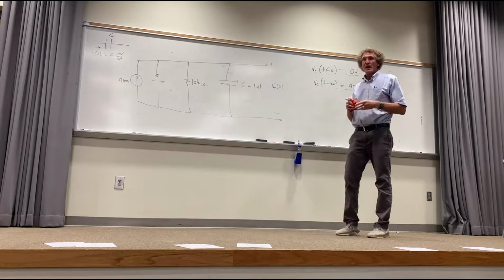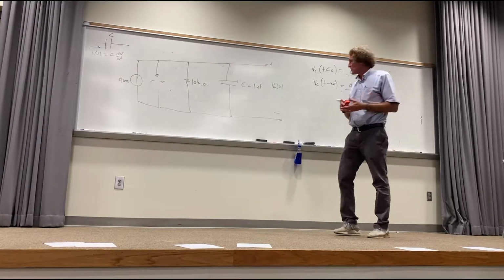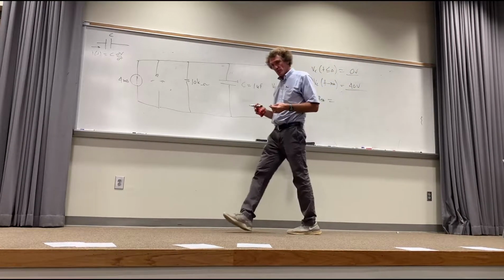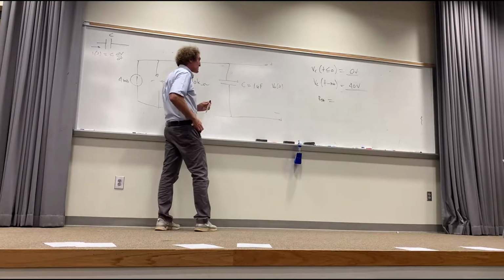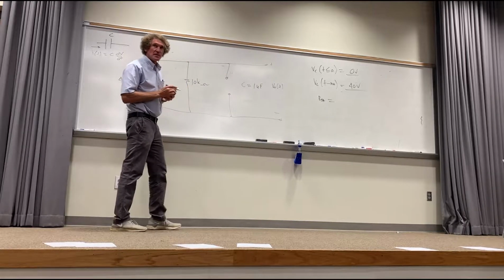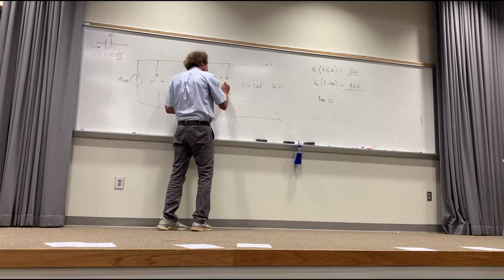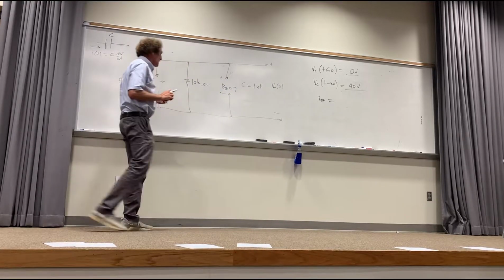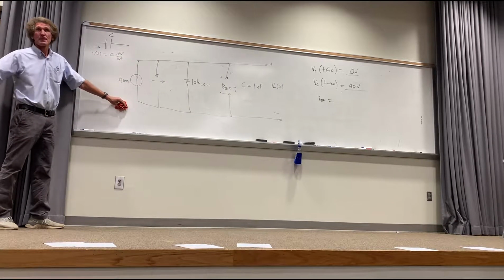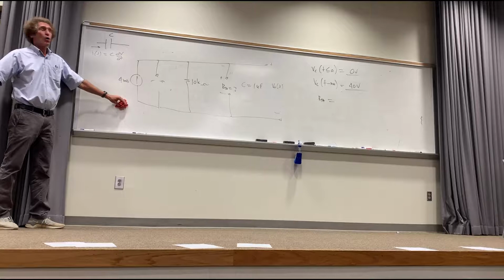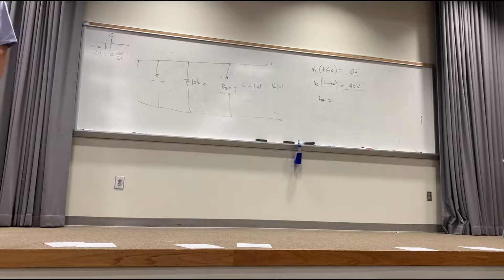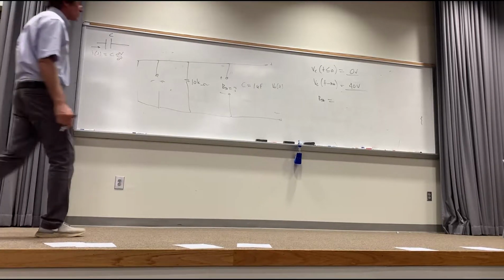Right? Now, after that, we find something called R Thevenin, right? And R Thevenin does what? You can do this until you get used to it: just erase the element and put in 2 little dangling leads, and we want to know what the resistance is here. That's R Thevenin. Now, we have to turn off the sources, so when I turn off a current source, what does it become? Class? Open circuit. So how much resistance is between those 2 dangling leads? It's just going to be the 10K ohm.